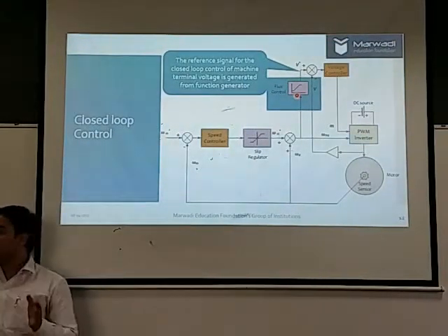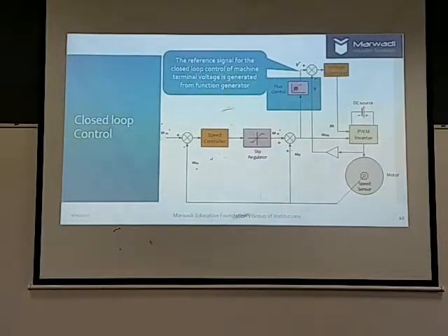Okay. Now this voltage, as shown here as a straight line, will follow the frequency linearly, but above base speed or above synchronous frequency, the voltage will be maintained, because we cannot increase the terminal voltage of the motor.